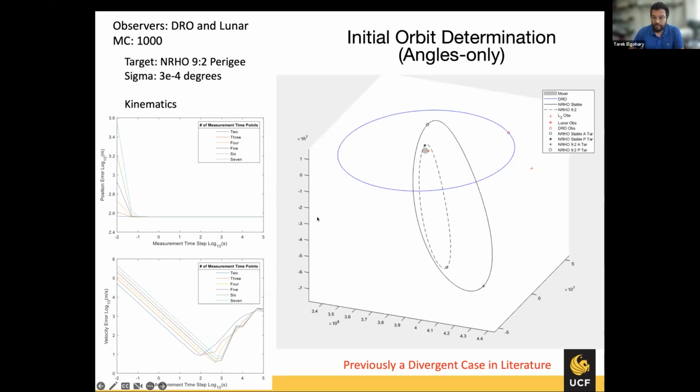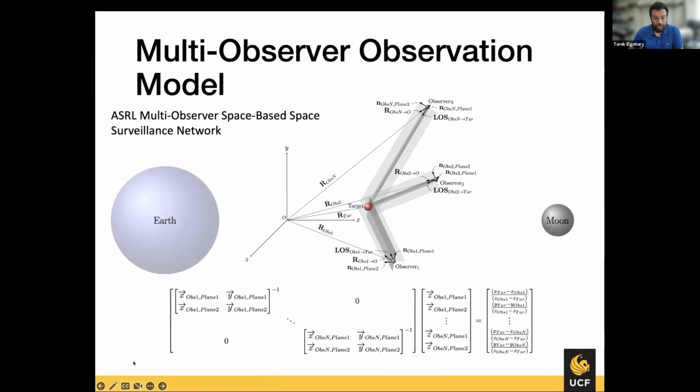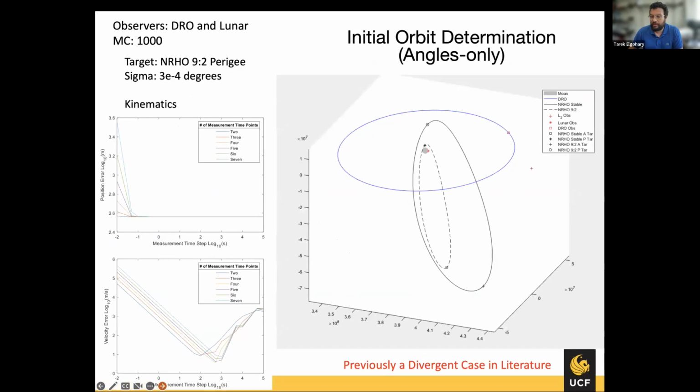One of the areas that we're researching beyond this is, can we take measurements in an asynchronous fashion? Can we include different types of measurements beyond angles only, like angular rates, range rates, and any other types of measurements out there? The promising structure here allows for that. And also, we are trying to define what would constitute a bad measurement, how do we do the estimation process accurately, and various other sub-areas of that estimation process, or tracking an orbit in cislunar space.